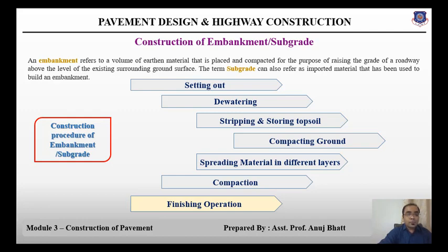The topsoil removed and conserved earlier shall be spread over the fill slope to facilitate the growth of vegetation. The slope shall be roughened and moistened slightly prior to the application of the topsoil in order to provide satisfactory bond.